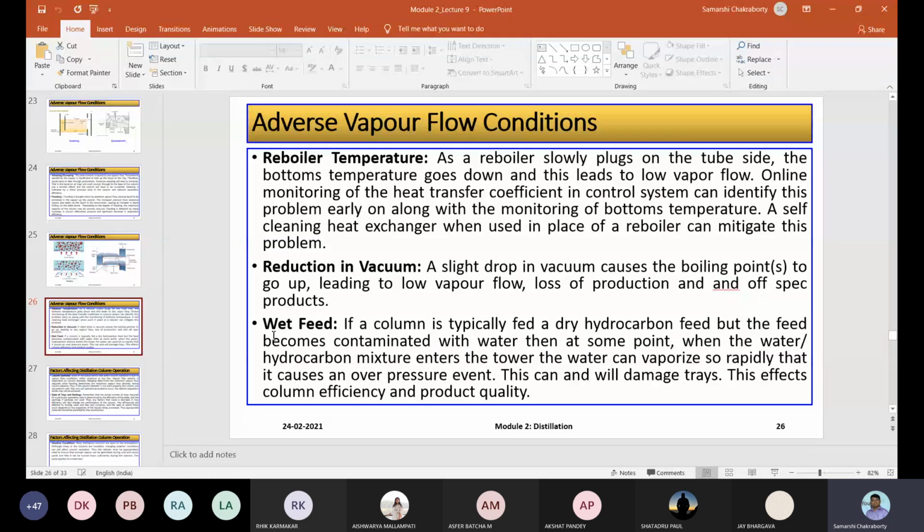Whenever you are dealing with a heavier petroleum fraction like reduced crude oil, as I have told you while talking about the vacuum distillation unit, if I want to distill spindle oil, a heavy intermediate oil, at normal atmospheric pressure, it has to be distilled at approximately 500 to 600 degrees centigrade. At that temperature, if you heat it up, your crude oil or whatever products you are handling, your reduced crude oil, is going to thermally degrade.